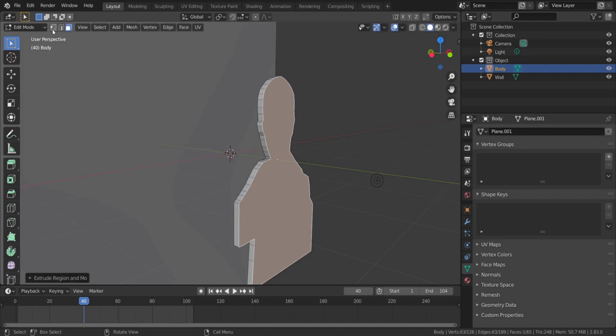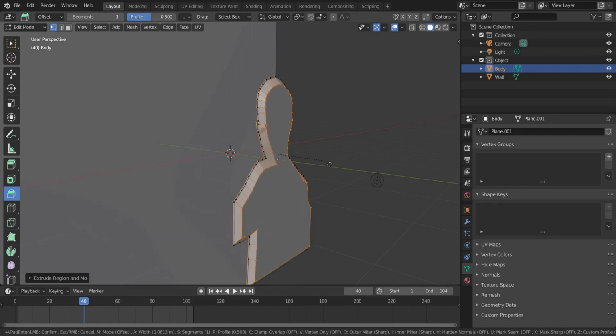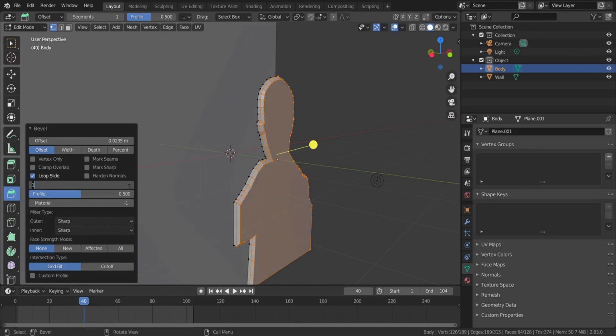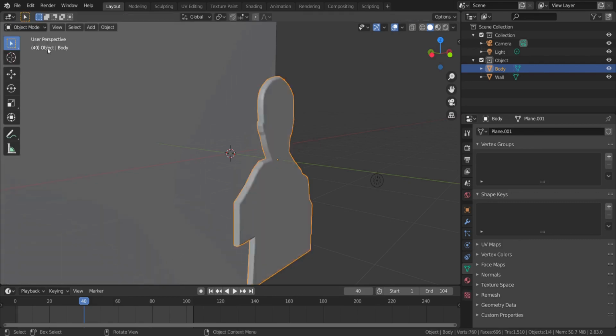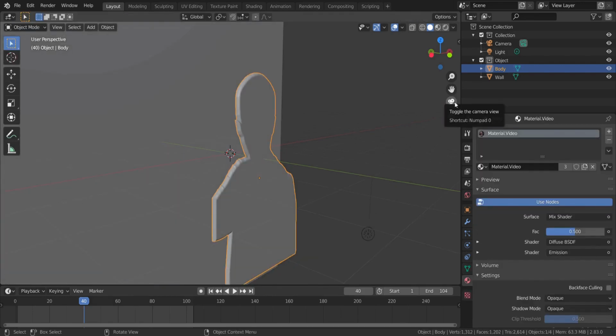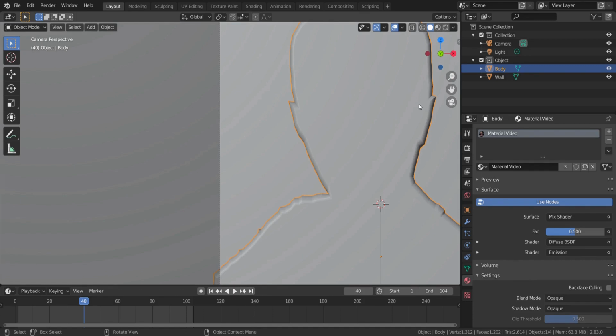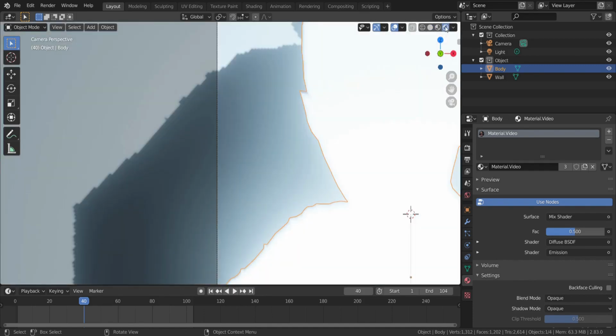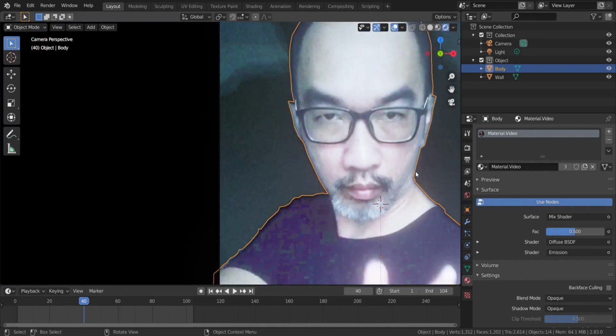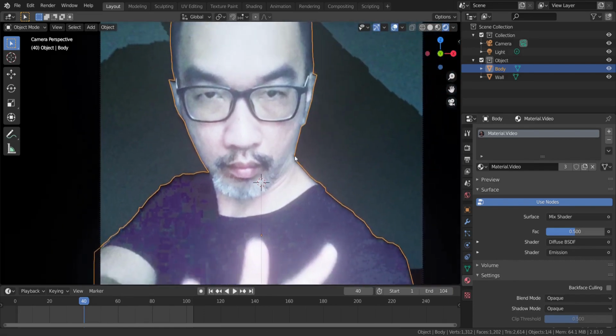After that, change to vertex select, click bevel, and hold the yellow handle to bevel out slightly. Be careful when you bevel out. If you see some artifacts, then you may have to reduce the beveling a little bit. Once you're done beveling, just left click. After that, go to the option on the bottom, give it 10 segments. You may also want to change the offset to see fit. Now, zoom back into the camera view and turn to render viewport. Now you should be able to see a much smoother light and shadow gradient along the edge.